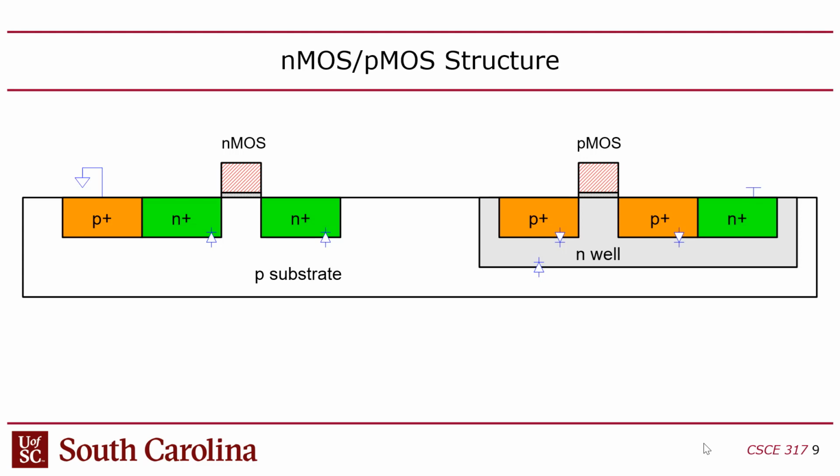And you don't want any current flowing between the diffusion areas and its little well, which is its localized area of substrate. So if you bring the N well up to VDD, then you know that this N well has a higher voltage potential than this P diffusion area, and so it'll reverse bias that diode. Make sense?